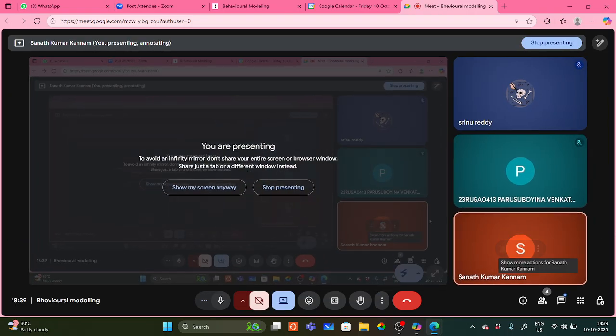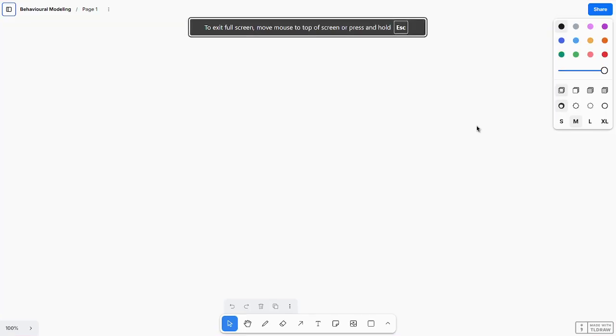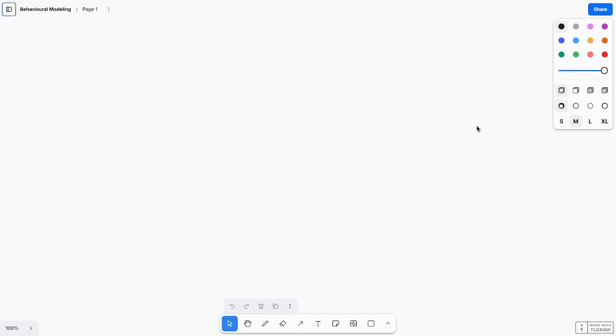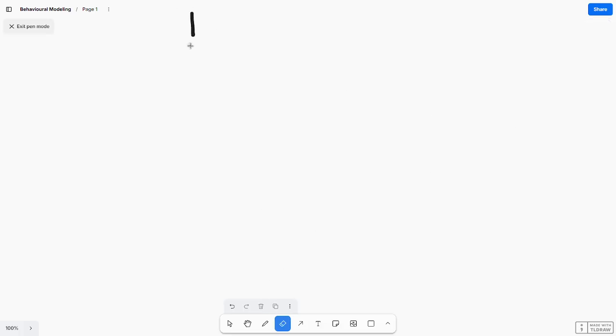Today we'll start behavioral modeling in Verilog. Behavioral modeling and data flow modeling together are what we call RTL code. Behavioral modeling, as I told you in the starting class, means we know the behavior of the circuit, so there is no need to worry about the internal circuitry. Suppose you consider the half adder: I know the behavior of the half adder, but I don't bother about its internal logic or circuit. That is behavioral modeling. We'll see it today.